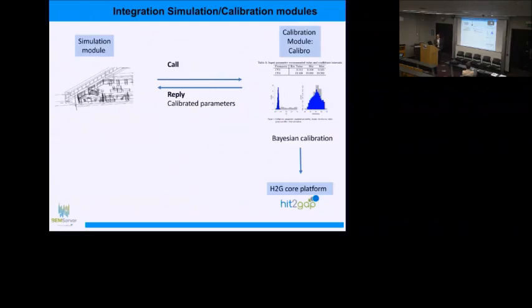And this is the point where HitTheGap and BEMSERVER becomes so important. Because when you click assessment there, what our tool is going to do is go to BEMSERVER, get the measured data for that room, inlet temperatures, outlet temperatures, flow rates, and we will use this to calibrate that model for that particular day in such a way that you have a very good agreement between simulation and actual measured results, and increases the reliability of that data.